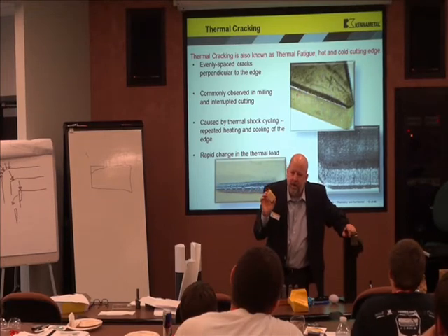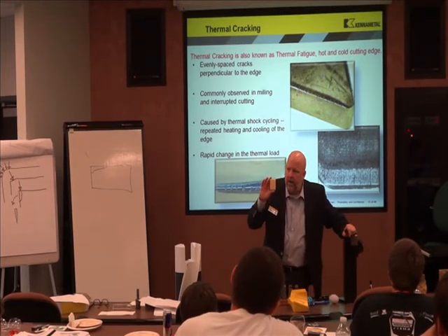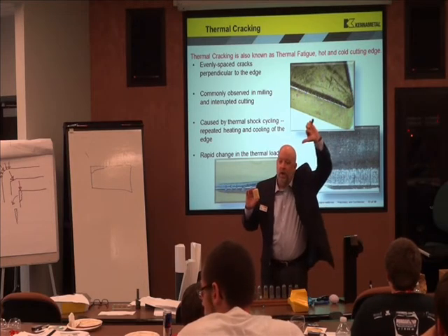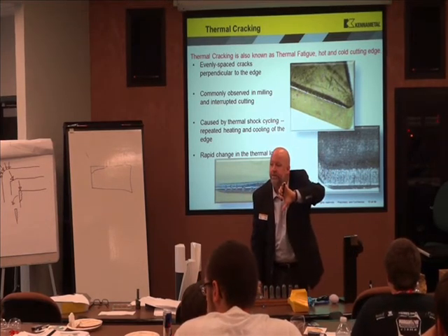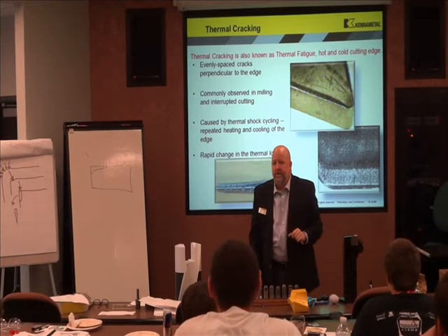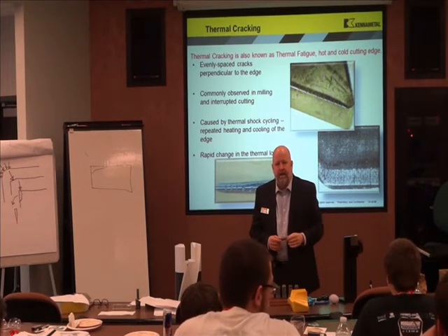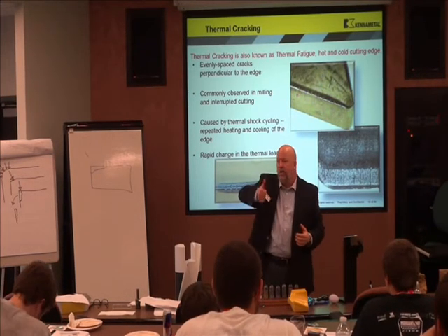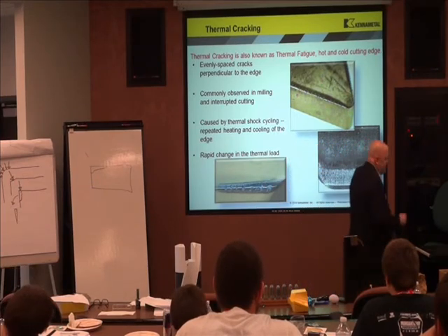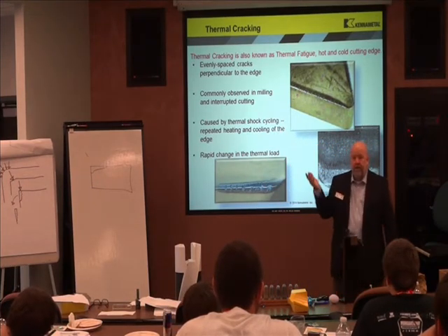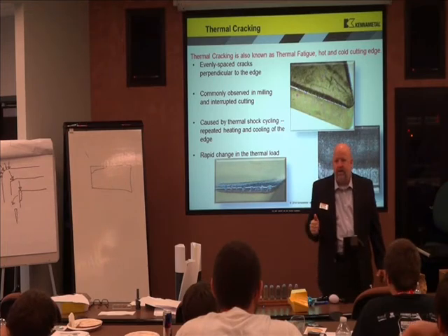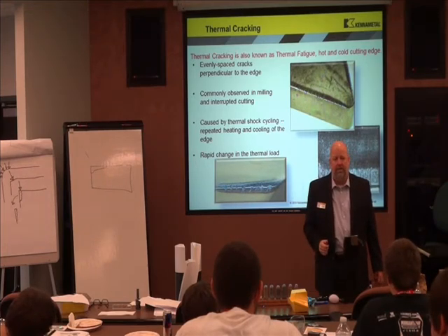Every manufacturer of carbide, their carbide grades in milling that they say to run wet, you have to run them at slower surface finishes. A lot of people don't realize that. The grades that you run dry, you can run faster. That's counter. So here's the truth. I cut the coolant off. 90% of the time I get 30% more tool life in milling.